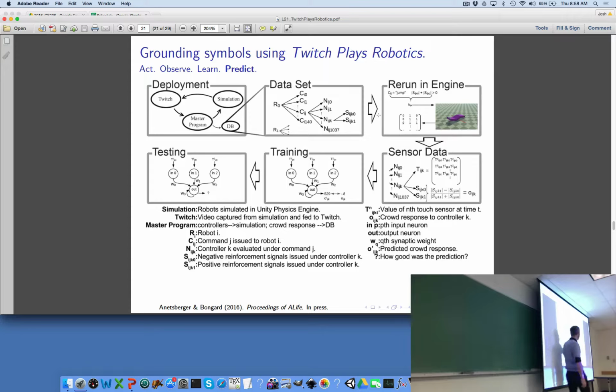What features of this matrix, which is just a binary matrix of touch information, either the touch sensor was firing or it wasn't, allowed the neural network to predict that this matrix encoded a jump or it didn't? There's a time point where no touch sensors fired. Could be, right? That would be my first guess, that there were certain rows in this matrix that were all zeros. All the body parts of the robot were off the ground, perhaps.